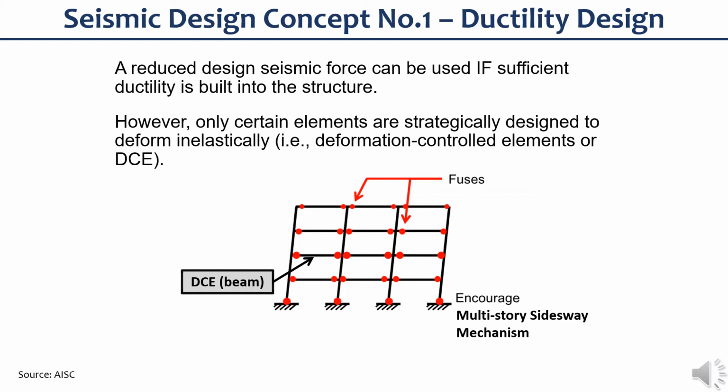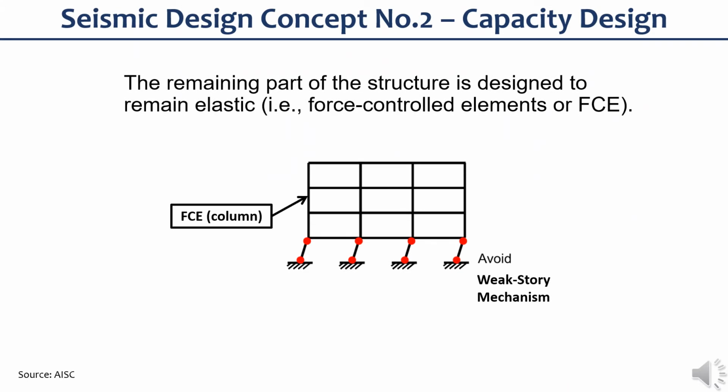In this concept, we need to, number one, provide yielding elements to control overall force. It's basically to make sure the fuses are ductile. And second, to protect the non-yielding elements, that is to estimate the maximum force from the fuses.